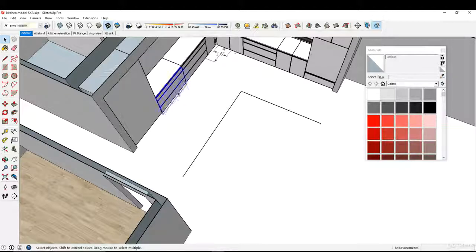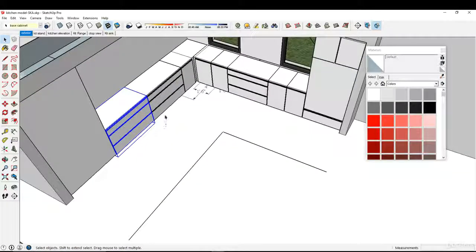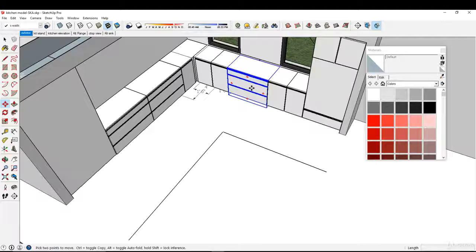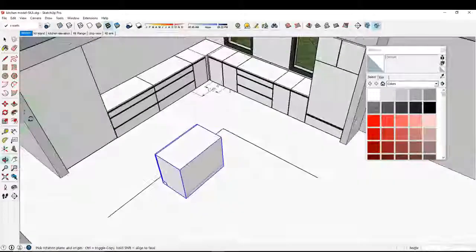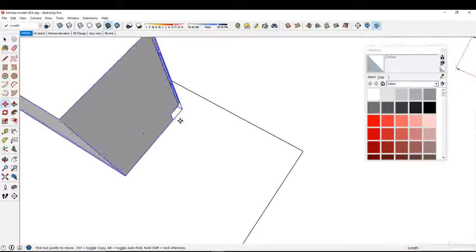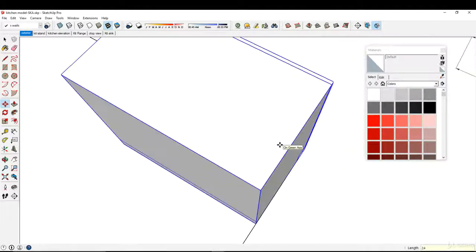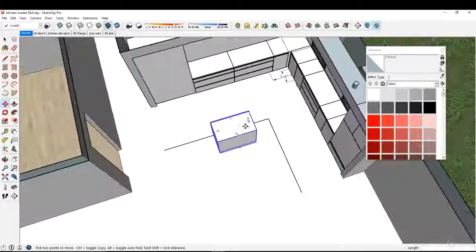and this is where my sink cabinet is going to be as well. So I want it to be this 3-drawer cabinet style for my sink cabinet. So what I want to do is grab this, and actually I'm going to use the 42-inch cabinet for that. And let's go ahead and rotate it. Rotate it 90 degrees. And I'm going to start it at this point, but I'm going to come back 24 inches. And actually I'm going to come over 24 inches here.